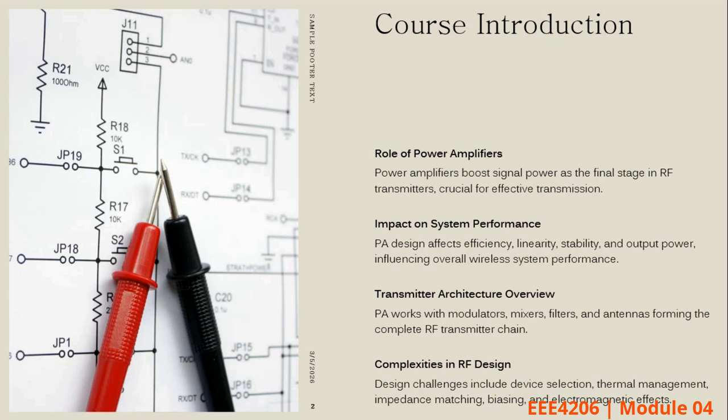Okay, so the architecture for the transmitter has different blocks. First and foremost, we have the RF input, and this is normally the one that receives the modulated signal. Then you do the input matching, whereby you ensure that the maximum power received from the modulated signal is transferred to the next stage.